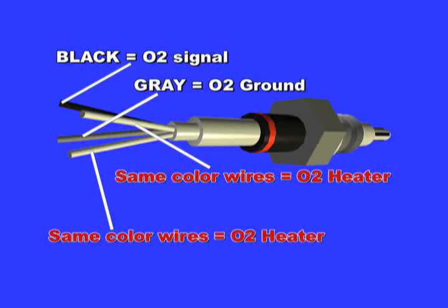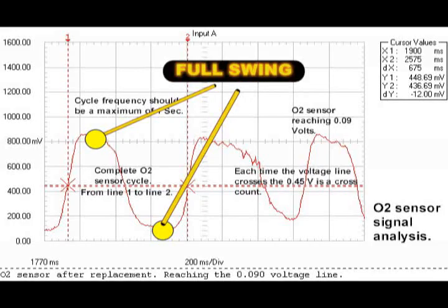The ADP Scan 1 is sufficient to test the O2 sensor. But if the ECM reading is wrong, as in a faulty O2 ground, the reading will also be wrong. Beware, the O2 ground may be different than the general ECM ground. Goose the throttle to wide open a few times. If the O2 sensor signal is swinging from 0.1 to 0.8 volts, then the O2 sensor is connected.